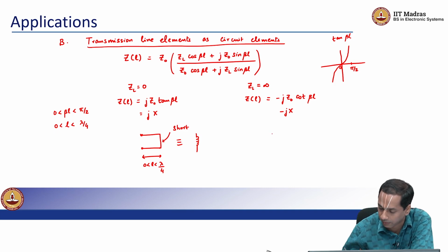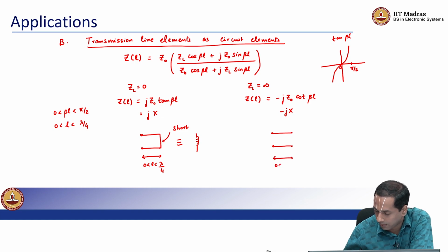And similarly here, if I have an open circuit transmission line of length between 0 and λ/4, this can actually mimic a capacitor.